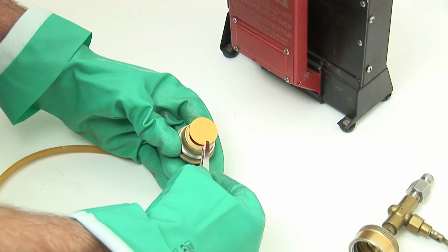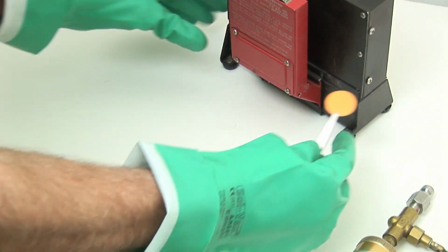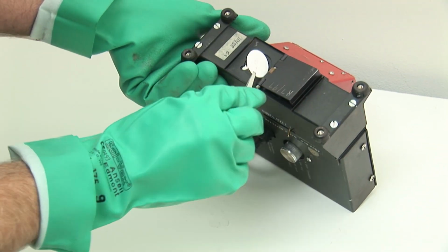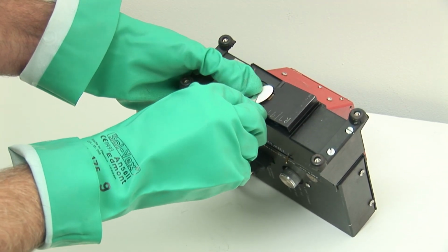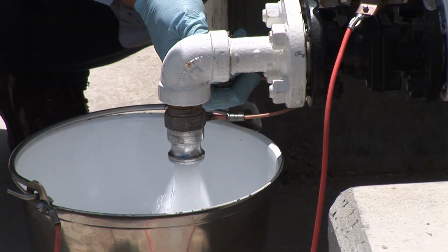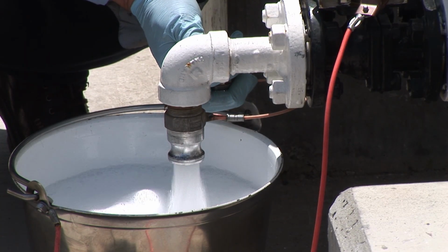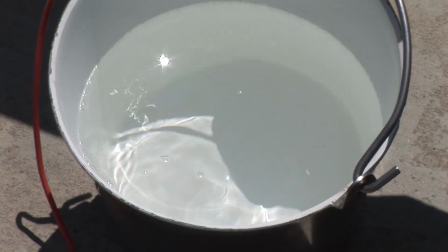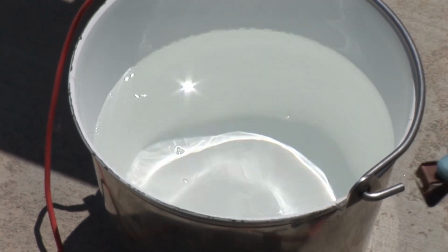In the AquaGlow test, you sample fuel through an absorbent filter pad and subject it to an ultraviolet light source. Water will cause the dye on the pad to fluoresce in proportion to the concentration. The white bucket test is used for filter separators only. Fuel and water are drained into a white porcelain bucket. The liquid is then checked for contaminants.